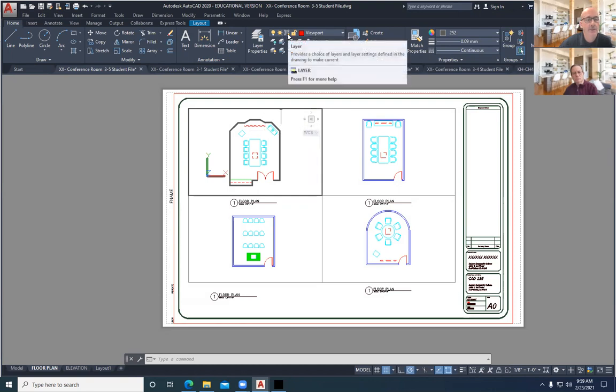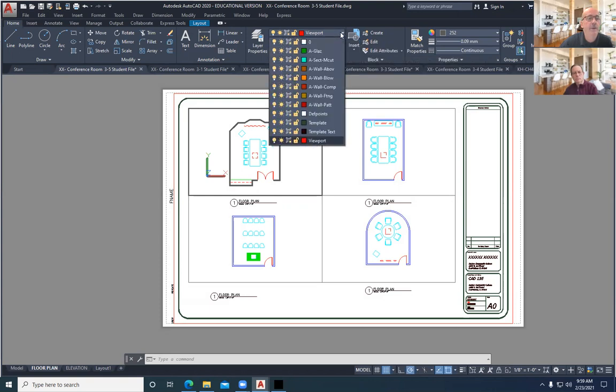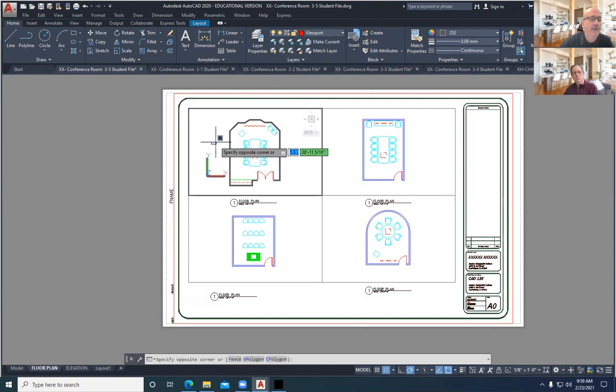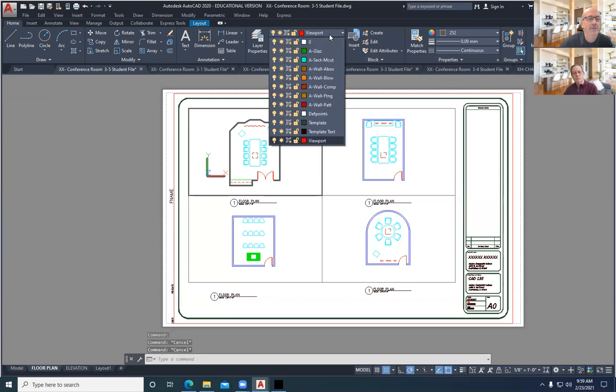And so this third button right here is called Viewport Layering. What I can do is turn off different layers within the drawings. If I look at what layer was that created on, layer 0, and I'm a little worried that we didn't create enough layers here to show it, because I have a feeling I'm not going to be able to turn them off because they're set. But this third layer here will allow you, for example, if I turn off layer 0 here, everything disappears. I turn it back on, it shows it again.